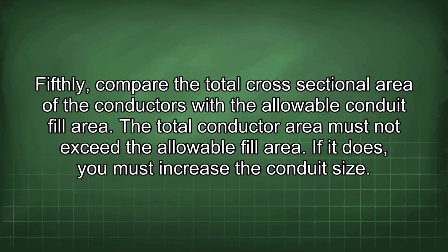Fifthly, compare the total cross-sectional area of the conductors with the allowable conduit fill area. The total conductor area must not exceed the allowable fill area. If it does, you must increase the conduit size.